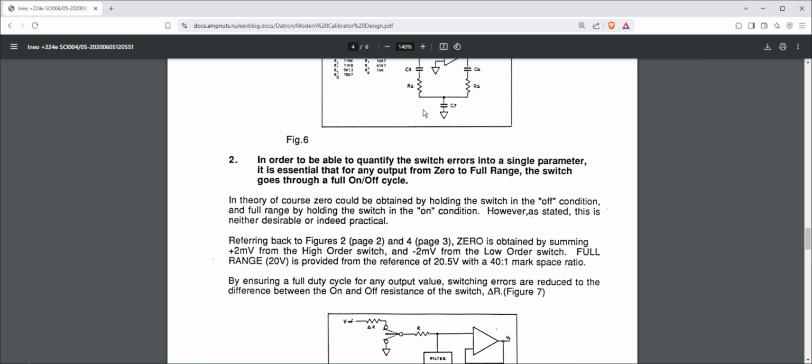It was Mark who figured out that this was happening because of the PWM and sample signal edges lining up, and this was proven by simply moving the edge of the sample signal by a few counts, which correspondingly moves the spike. With enough counts, the spike is moved entirely out of the output range of interest, finally resulting in a spotless plus or minus 0.1 ppm INL.